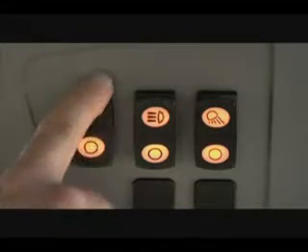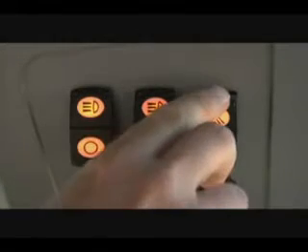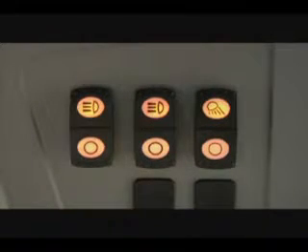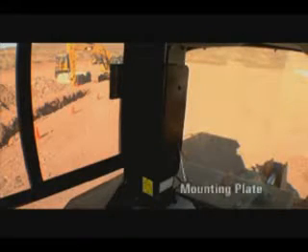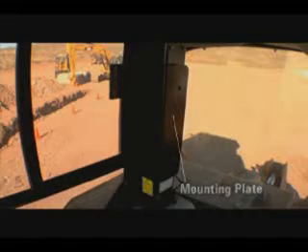Switches for the lights are located high on the right B post. These three switches control the headlights, blade, and rear implement lights. A mounting plate for a CB radio is located on the right C post, which means you won't need to drill into the ROP structure to mount your radio. A wiring connector for the CB battery and key switch power is in the right side console.